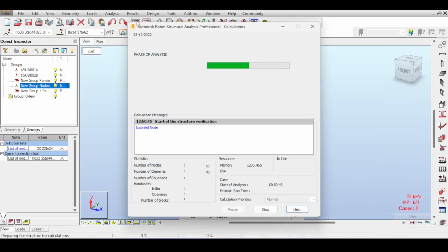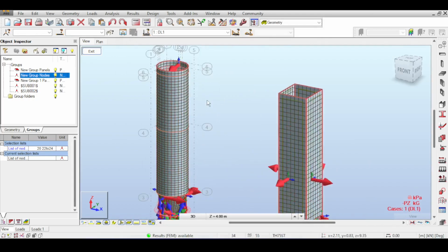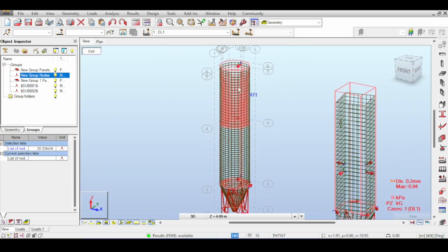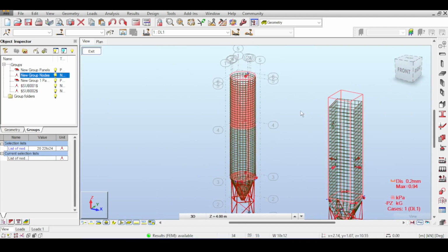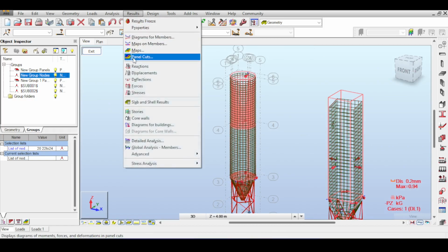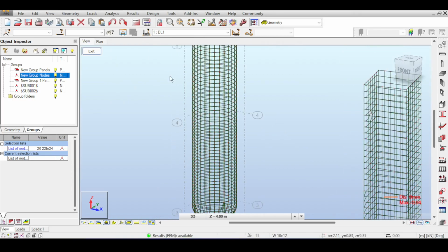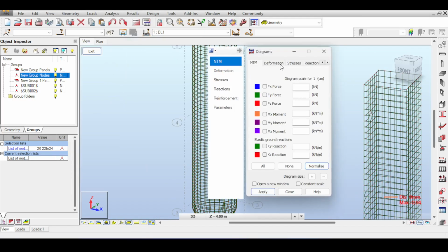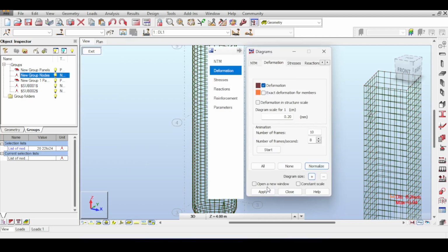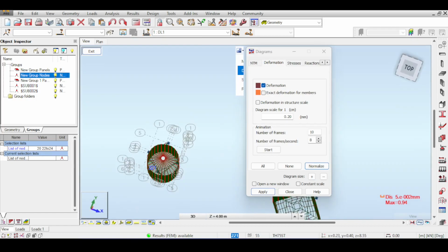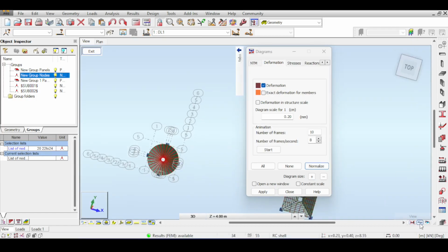All right, I want to teach you that you should sometimes take a step back and second guess yourself to check if everything is right or not. If you run the analysis now, what happens? Let's see the displacement. I refresh everything, open deflection shape, increase the deformation scale, and take a look if it bulges or not, because I'm expecting it to bulge. It does, I think. Let me tap 1, 2. Yes, it's bulging. You can see that when I toggle deflection and non-deflection, it bulges.